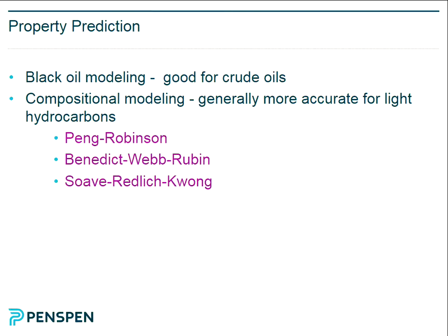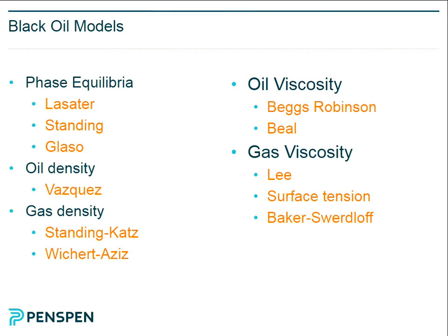And again, it's not something you need to memorize, but the important thing you need to know is that with multi-phase flow correlations, there are lots of different correlations for different sets of circumstances. A very famous one is Beggs and Brill. They're some of the very earliest researchers into multi-phase flow at Tulsa University. Some of the early research was done with water and carbon dioxide by Beggs and Brill in little 2-inch pipes.